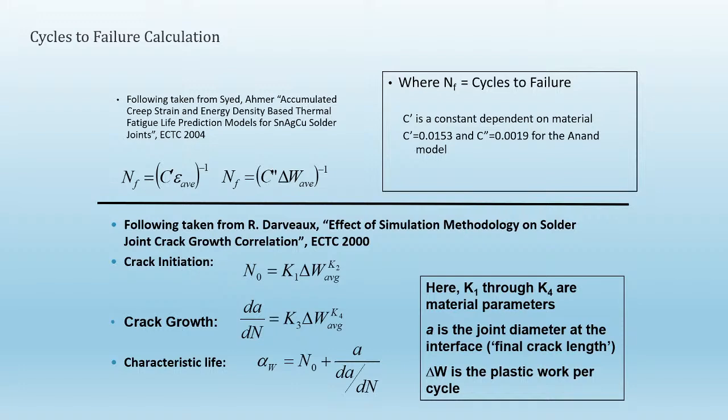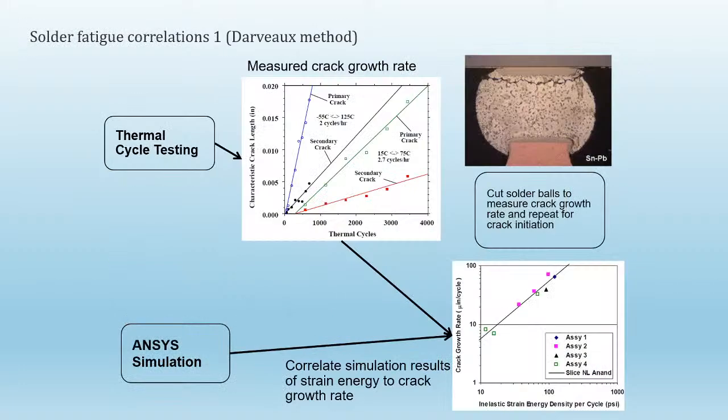Do you think using cohesive models to represent energy? Yeah, so I think cohesive zone models and looking at solder joint from a fracture mechanics perspective is very promising. Obviously, if you look at the failures, it's definitely fracture mechanics related, right? So it is a crack that grows through it. It's an interfacial crack often. In this case, it kind of goes through the solder.